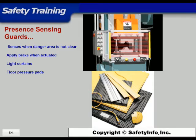Presence sensing devices detect the presence of a person or part of a person in a defined area and prevent the dangerous parts of a machine from moving when the danger area is not clear. The most common presence sensing device are light curtains. These devices immediately apply a brake or prevent actuation of a machine if the light field is broken by a body part or other object.